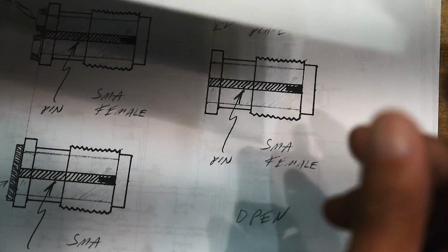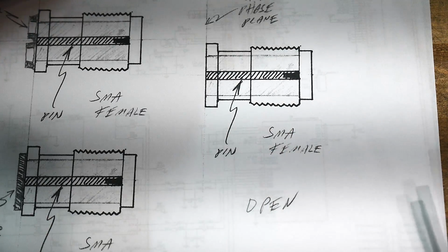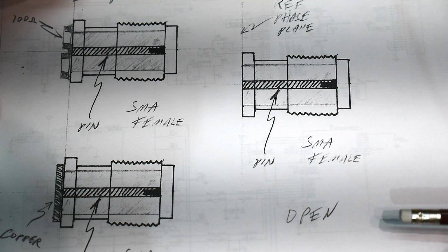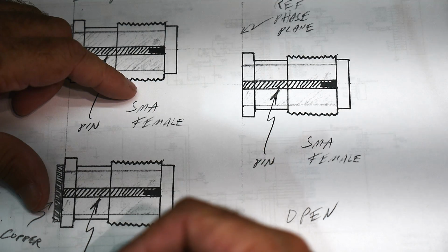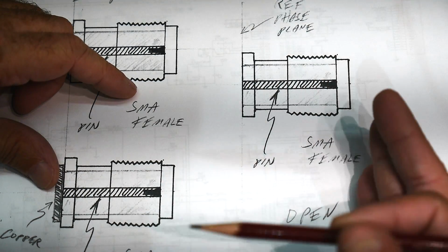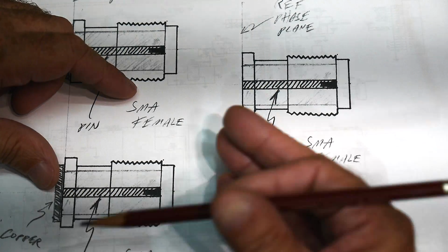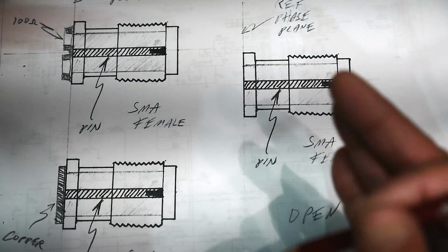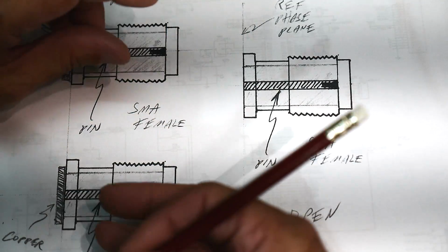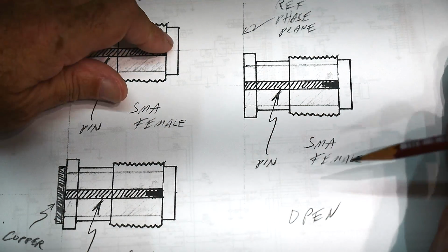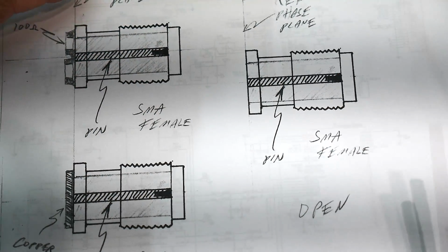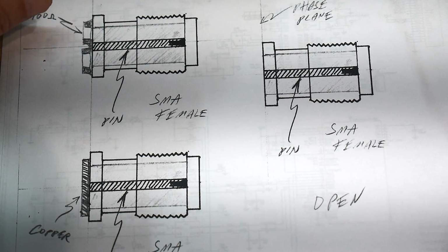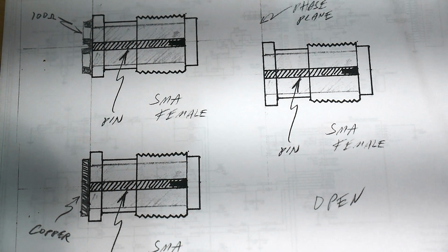All right, so we're going to use these three things, open, short, load, to do the calibration. Now, why are these chosen? Well, an open will allow you to measure phase of a known type. If you have an open, you know the phase is 0. If you send something down a transmission line and it reflects off of nothing and it comes back, it's in phase. If you have a short and you send a signal down a transmission line and it sees a dead short, it comes back out of phase, 180 degrees out of phase. Okay? And so we need to create some type of calibration standard.